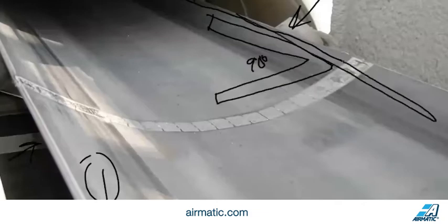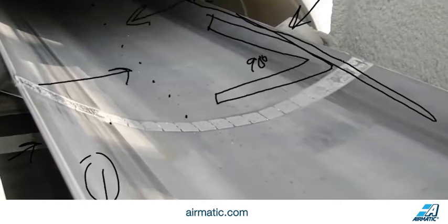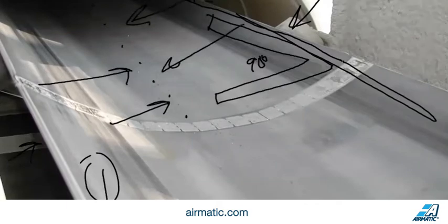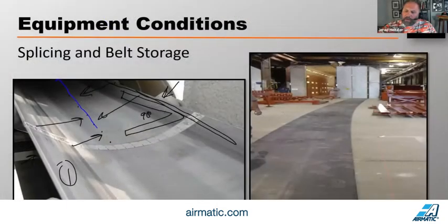What you need to do is create what's called an average center line by measuring half the distance from each side of the belt, striking marks, and then connecting those marks that you've created with a chalk line. That's giving you your average center line. Square off of that.